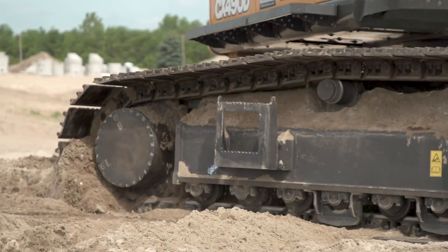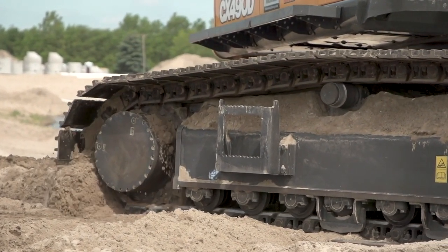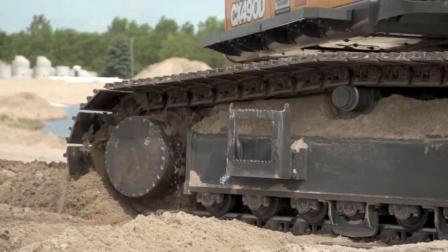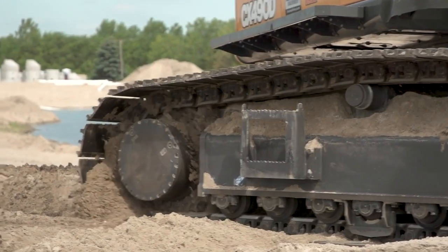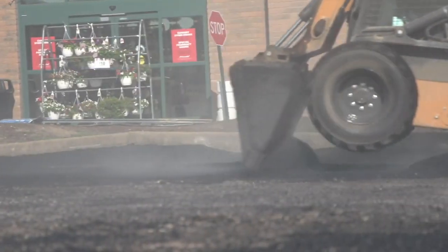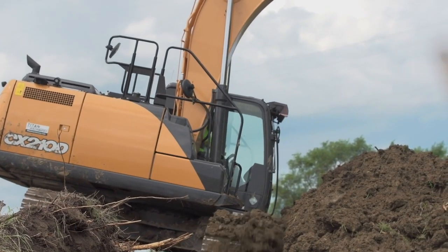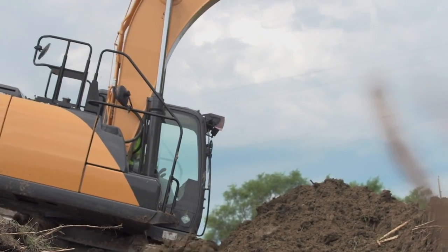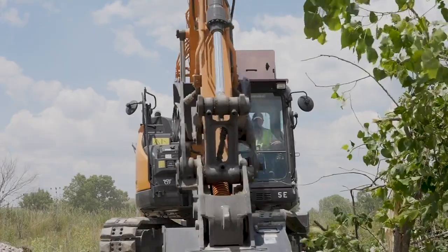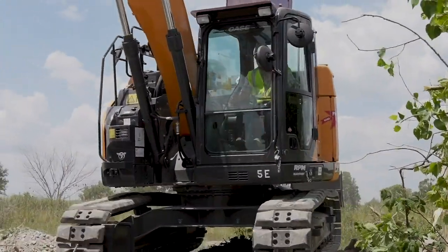One of the things that it allows you to do is concentrate on those tires and tracks and make sure that things like dirt, debris, and rocks are out of that undercarriage or out from underneath that rotating group. You can inspect the rubber components to make sure that you don't have any large nicks, scratches, or cuts that might lower the life expectancy or even upset your operating day that day or in the near future. So that review of the machine gives you the ability to understand and be ready for work that day.